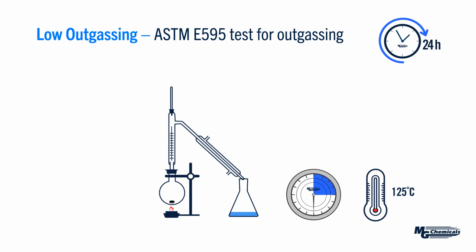And then basically what they will do is connect it, and you're looking for two things here. You're looking for how much off-gassing that material accumulates over 24 hours. So that's typically just a before and after weight measurement. But the other thing here is that they'll attach this condenser apparatus, and some of that outgassing material is then condensed, and they measure the amount of volatile material. So that's how much material sort of condenses from that off-gassing.